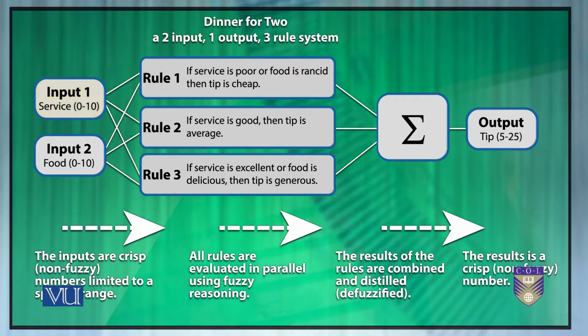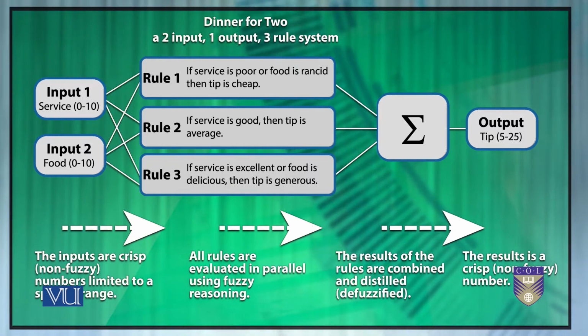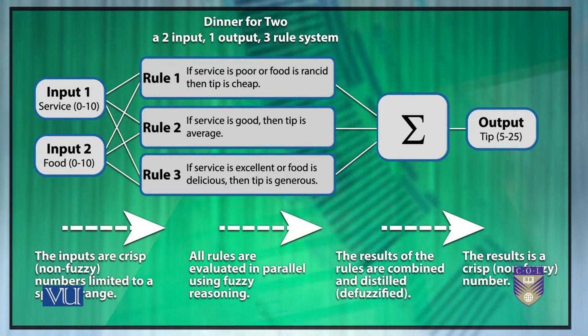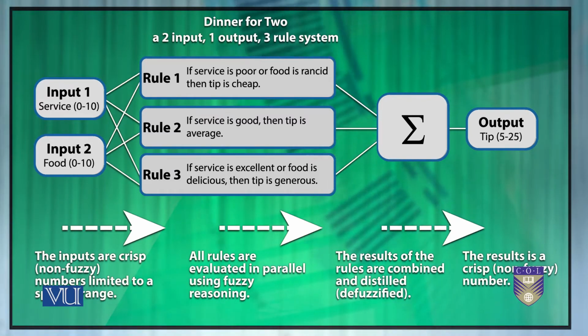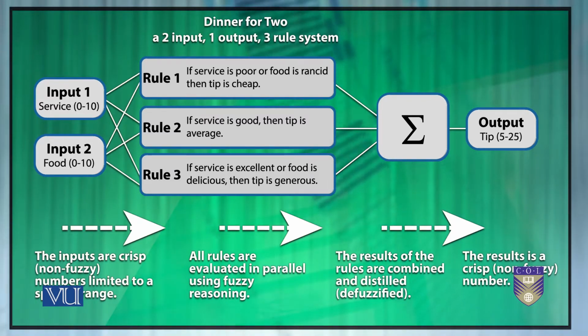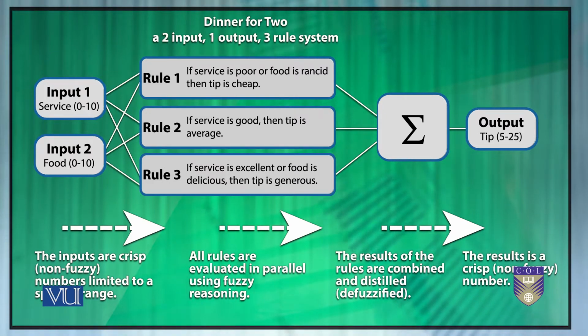And the output, the fuzzy degree of membership using the linguistic variable, will be in the range of 0 to 1. Fuzzification of the input is done either through a lookup table or a fuzzification function I mentioned previously, of course built using the 3 rules. And so you fuzzify the inputs.